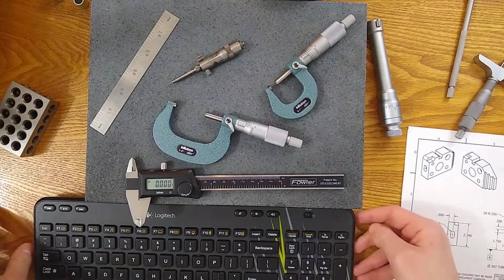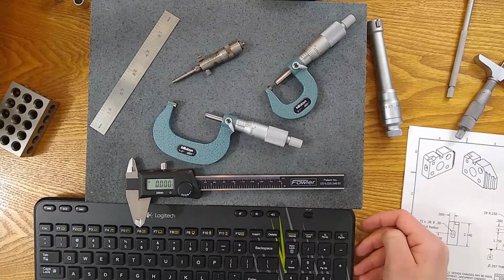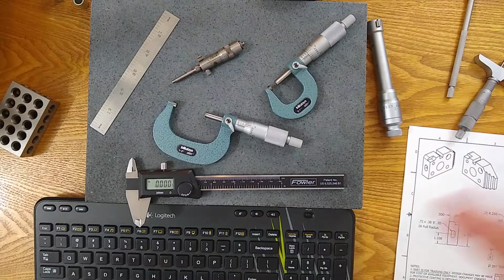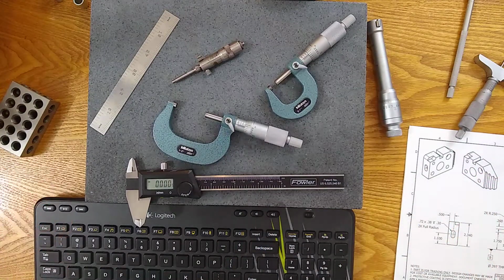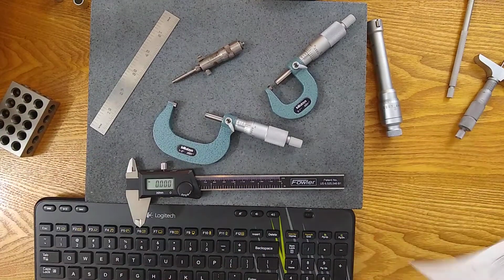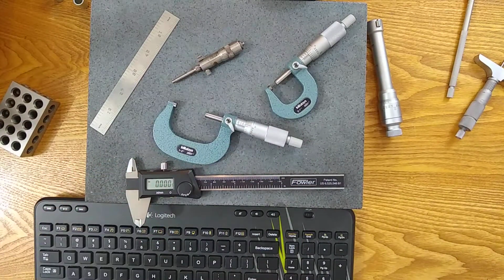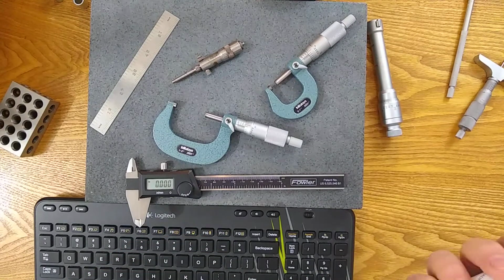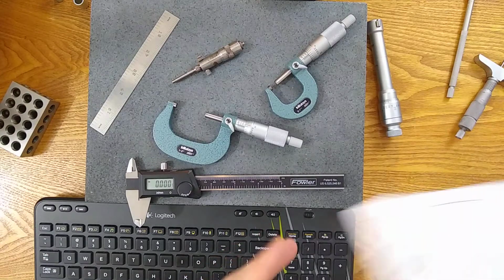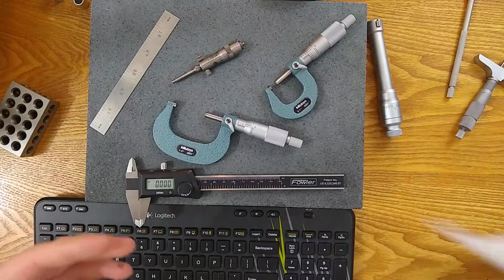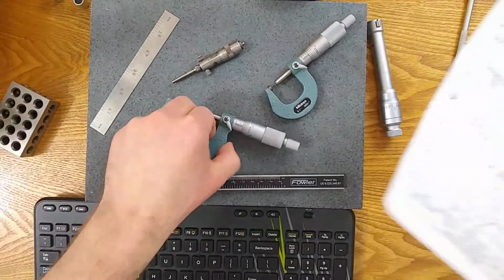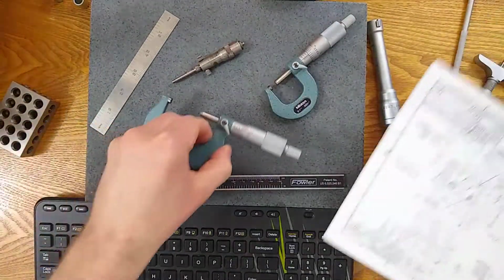So going through those 8 questions, right, whether you're using them or not, there are some major considerations that you have to consider when you're making a choice about what gauge you're going to use. And every choice may not be weighted the same. Some are minor, some are critical, and many are just average, have typical impact. So from a metrology standpoint, what you're considering: tolerance zone, the gauge accuracy, and the fixtures you're going to use.